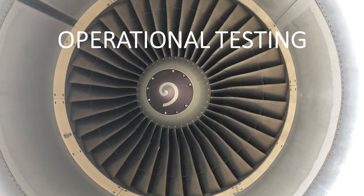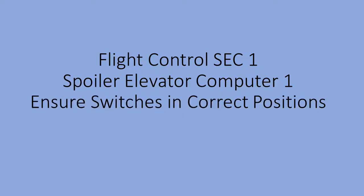So, there's that, and then your flight control SEC 1, because those are your elevator computers. Your switches are also there. You want to make sure those are in their correct positions, and of course install warning notices on levers and whatnot, anything that will keep people away from manipulating them while you're doing an operational test.